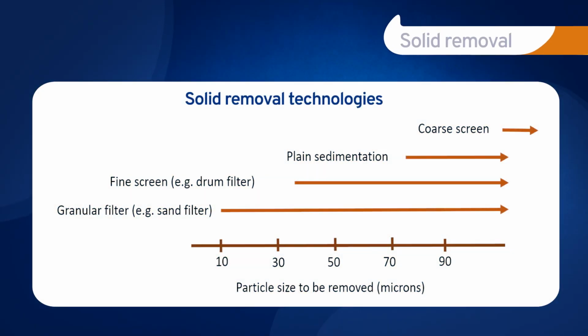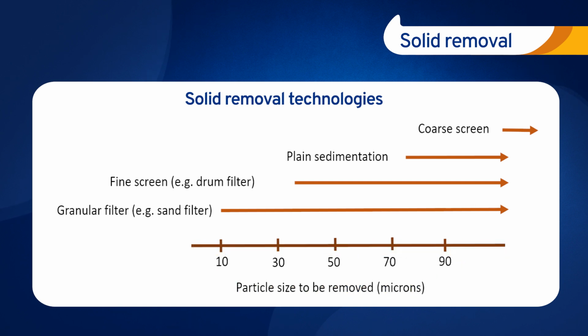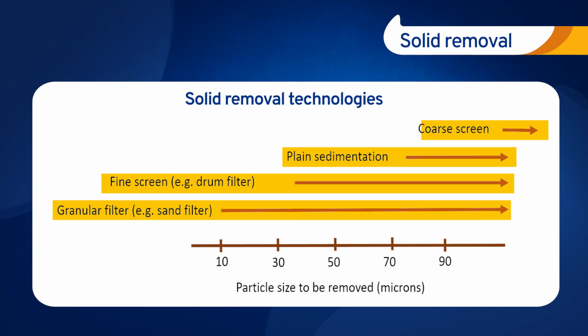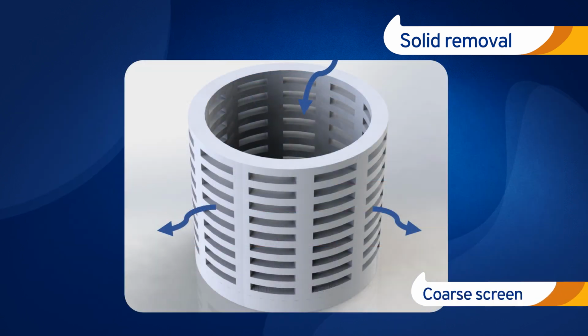There are several methods to remove coarse and suspended material based on its properties. As one can see, the methods depend on the solid particle size, ranging from large solids to fine ones. Mostly these methods include screening and sedimentation and finer filtration units, such as drum and sand filters, and for the very fine dissolved particles, all sorts of membrane technologies, which will be discussed in another section. Larger solids are typically trapped by screens such as this to remove waste like wipes, sanitary products, and larger debris.